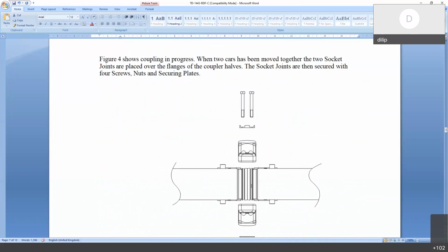Very much similar to the Shaku coupler of EMU coaches. Yes, similar to the Shaku coupler. In Shaku, we have these hinges which are rotated and it is more or less similar. Basically, Shaku is nothing but a semi-permanent coupler. But the Shaku draft gear is different, whereas the draft gear of this one is the same as CBC. The Shaku coupling may not be suitable for hauling 20 or 24 coaches, whereas this particular arrangement can haul 20 or 24 coaches. The arrangement is similar. There we have the rotating type of hinges. Here they are properly fastened by screws and nuts.